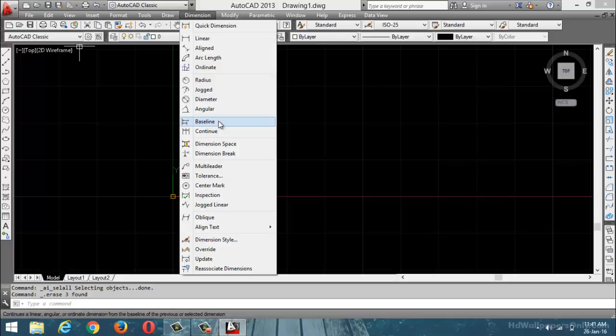Now see here. First one. Now this is my base point. Now this start point is my base point. Again next. What happened? We can design all the dimensions of the component with respect to a single base point. Okay. Again next one is the continue dimension, for the same example. Continue means with respect to previous point, whereas baseline means with respect to base point. All the dimensions with respect to base point.